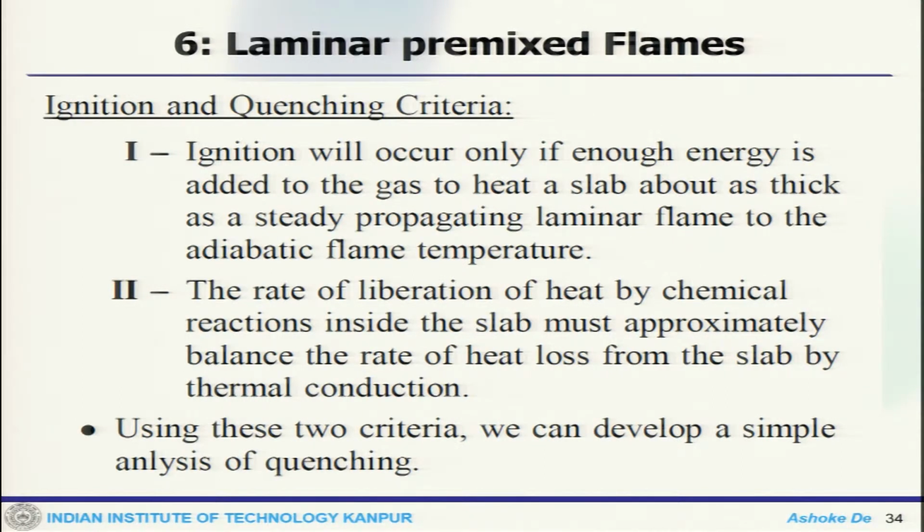Now, there are some criteria that one can put together. One is that ignition will occur only if enough energy is added to the gas to heat a slab about as thick as a steady propagating laminar flame to the adiabatic flame temperature. So, that is one criterion for ignition to take place.